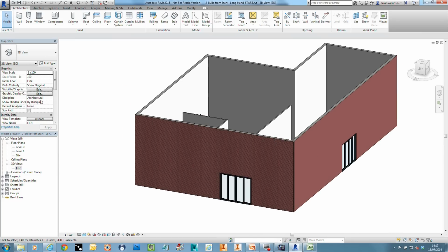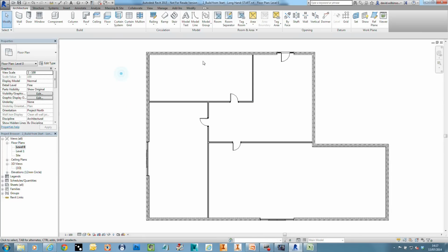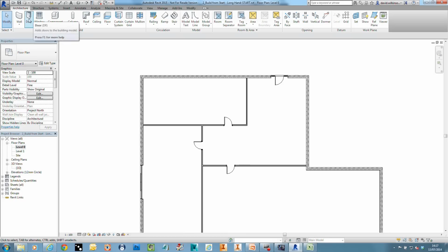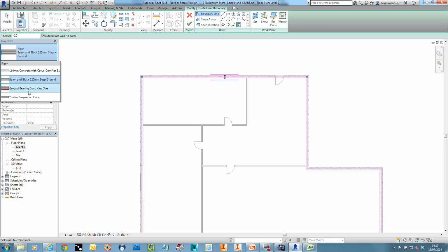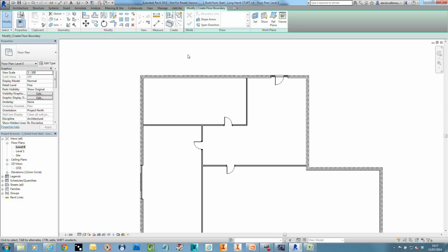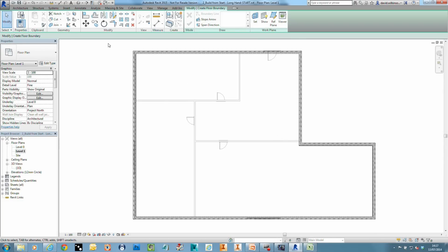Okay. If we go back to our level 0, we need to put a floor in there. So you'll notice we're just working, not quite left to right, but along this portion of the toolbar. We're simply going to come in and say I want a floor that connects to our walls, and it's this type of floor. So again, hopefully you can see that this properties area of Revit is very important. It's where we specify what we want to drop in. But we're not doing like we do in AutoCAD, where we're actually drafting lines, arcs and circles. There's my flooring.